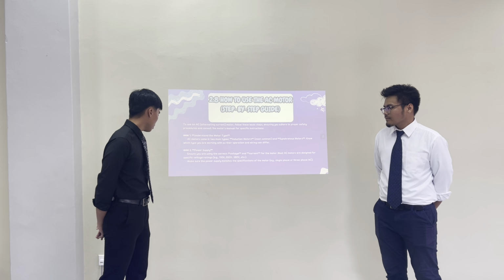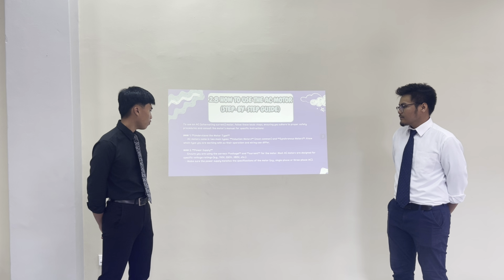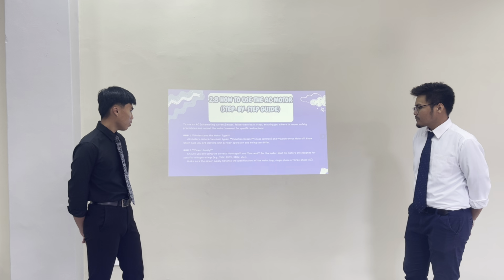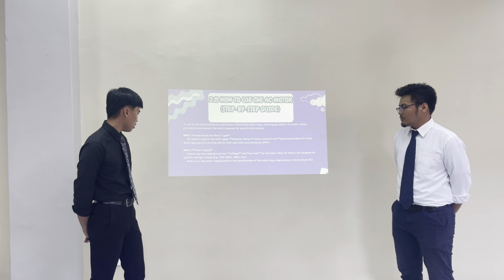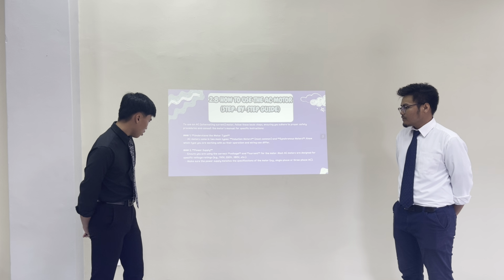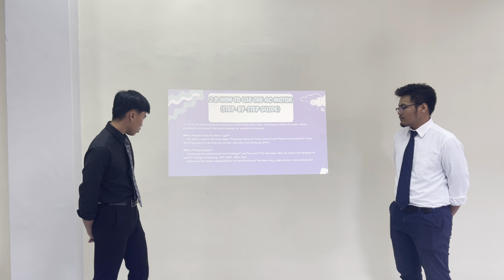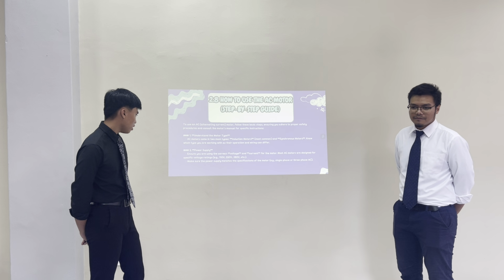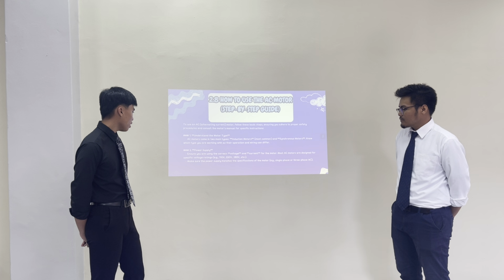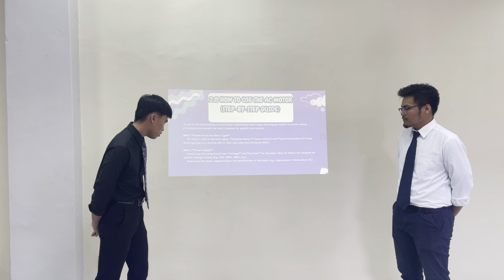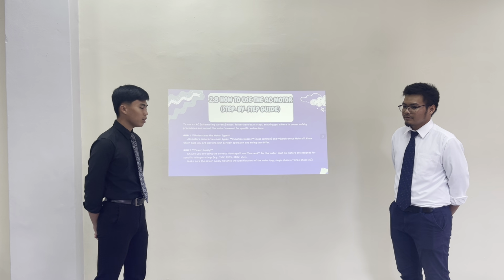2. Power supply. Ensure you are using the correct voltage and current for the motor. Each AC motor is designed for a specific input rating, for example 110 volt, 220 volt, or 380 volt. Make sure the power supply matches the specification of the motor, for example single phase or three phase.